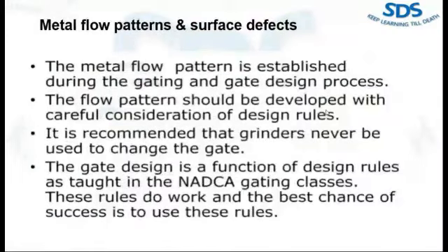The next factor which can contribute to surface defects is the metal flow pattern, which results from the gate design. This flow pattern is established during the gating and gate design process for the part, and there are some design rules that have been established for designing gating and gates, and they should be followed.